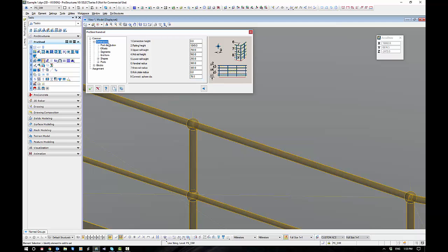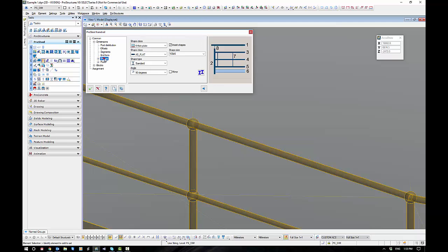Moving on, after I set the dimensions up, then I would move to shapes. In the shape type here, you've got your handrail, posts, etc. I can nominate my object type, its location, and whether I actually want it inserted or not. Also the angle is worthy of note too. I always try and push my blue ECS axes up, so just be mindful of that.